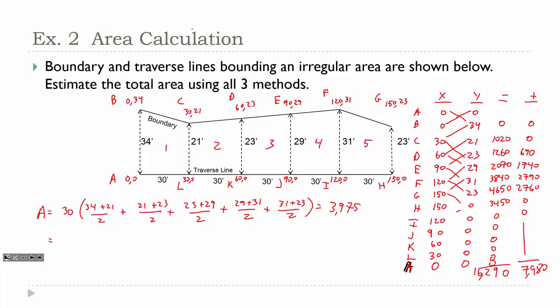All right, so Simpson's rule. So we have H1, HK. Somehow that's if you have an odd number of trapezoids or an odd number of measurements. So in this case, we have 1, 2, 3, 4, 5, 6. Assuming those verticals are the height measurements, we would need to have an odd number of measurements. So we wouldn't actually be able to use Simpson's rule in this case unless we disregarded this last section so that we had an odd number of measurements.